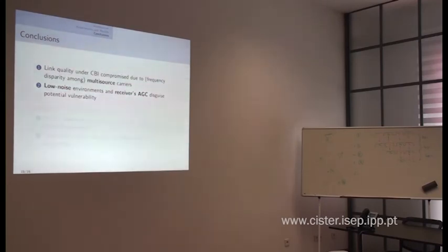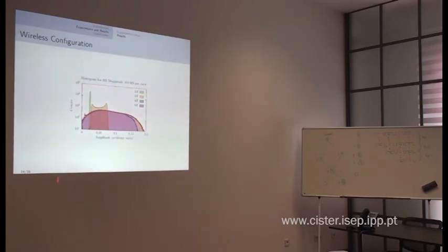So we speculate that the reason is that the experiments they conducted are in very low noise environments. They don't add noise. And there is also something interesting about this. If on the receiver side, after you transmit this messed up composite signal, you have a receiver that can dynamically adjust the gain of the amplifier chain to track this signal, then when it comes down here, it will amplify a lot.